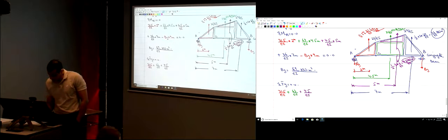You have this blue force, which is 36 divided by EI, and you have By, which is negative 69 divided by EI, and you have negative AY equal to 0. So from this equation, you can go ahead and find AY. Therefore, AY is equal to 66 kilonewtons meter square divided by EI.